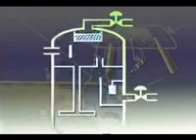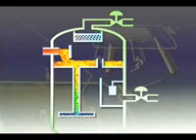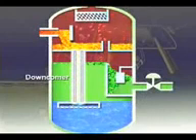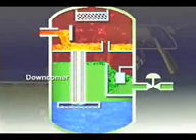In a vertical three-phase separator, flow enters the vessel through the side. As in the horizontal separator, the inlet diverter separates the bulk of the gas. A downcomer is used to transmit the liquid through the oil-gas interface to keep from disturbing the oil skimming action. A chimney equalizes gas pressure between the lower section and the gas section. The spreader, or downcomer outlet, is located at the oil-water interface. From this point, as the oil rises, any free water separates out from the oil phase. The water droplets flow countercurrent to the oil. Similarly, the water flows downward, and oil droplets trapped in the water phase rise countercurrent to the water flow.